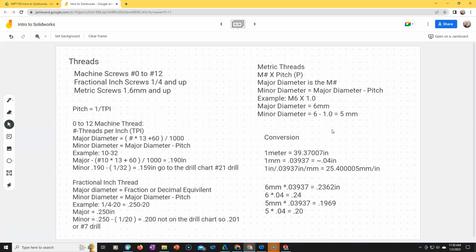Well, I look at the index or the drill chart, and I find that a 4.2 is really close too, but if I don't have that drill chart and I'm not carrying around a Machinery's Handbook, I would like to be able to do a quick conversion. And that comes back to 1 meter equals 39.37 inches. And we can go out 5 or 6 decimal places, but unless we're trying to calculate distances to planets, that 0.007 is not going to run into too much of an issue.